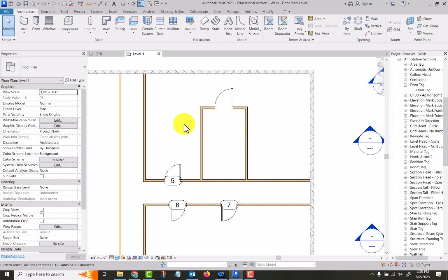But like where my office is, I'm in a hallway, my office is called 200Q. So my door on the plans would be tagged 200Q. All right, because every door needs to be an individual number because of the hardware, the swing, the frame sizes. There's so many variables they have to be tagged individually.